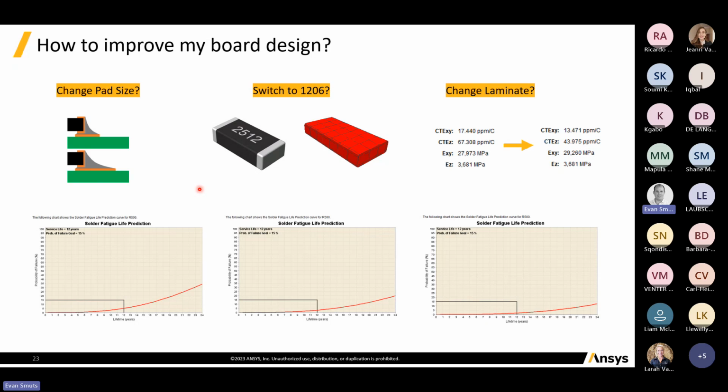This can all be done on the fly within Sherlock, because as much as you have your detailed ECAD model, your model of your PCB with all the different layers and traces and the positions of all the components, Sherlock does see it as a flexible system where we can move these components around and make changes to a lot of these parameters and do what-if scenarios.